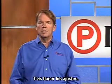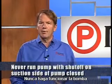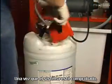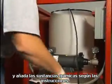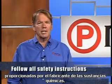After you make adjustments, make sure the valve is in the full open position and never run the pump with the shutoff valve on the suction side of the pump closed. After the system is fully tested, drain any water that remains in the primary tank and add chemicals according to the instructions. Remember to follow all safety instructions provided by the chemical manufacturer.